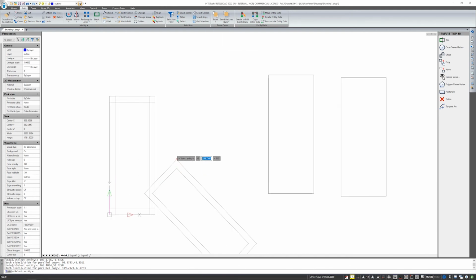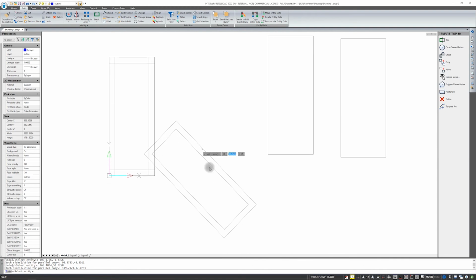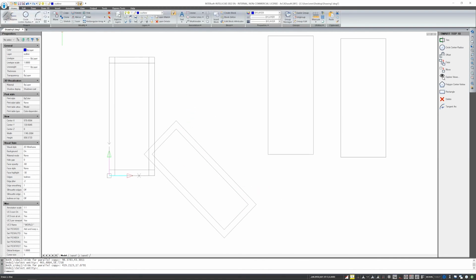In this rectangle, I will have to remove these intersection lines, unless I need them. If I were to go outside, the outline would be wider for this rectangle. But here, these lines would end up in exactly the same place, so I would have to lengthen them. So depending on what the elements will be used for later, you can choose different options.